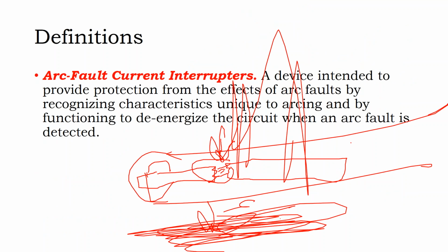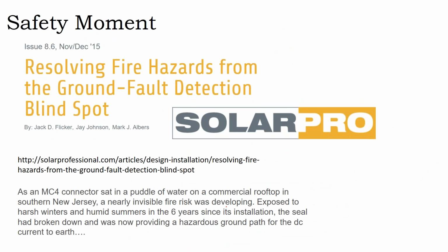It might be that you have wires pulling apart in an arc fault, but it's not arcing into your metal conduit, and you might have an arc fault that's not a ground fault. And I can tell you, arc fault is usually a workmanship issue. Ground faulting was more of a concern.